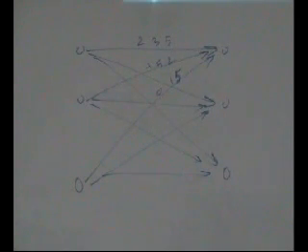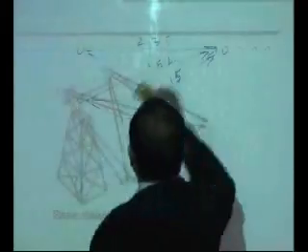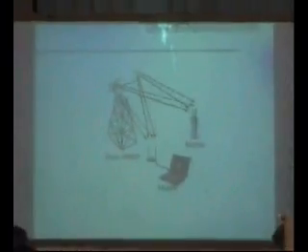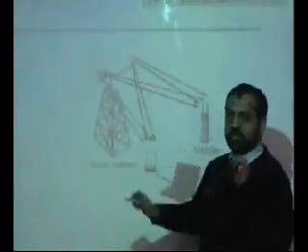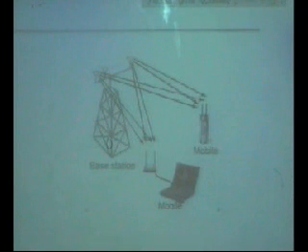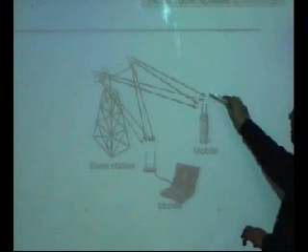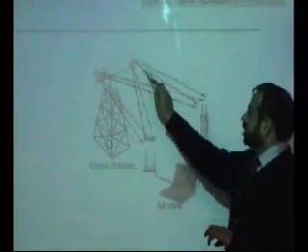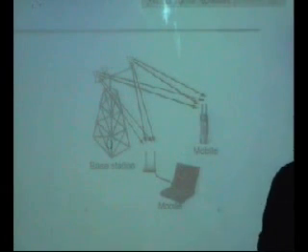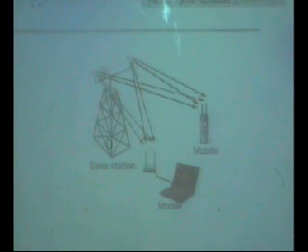So this is where the technology is moving, and these are called MIMO, multi-input multi-output systems. They are of special interest to us. Why? Because each antenna transmits a different stream of data. You are not transmitting the same data using all the transmitters. So what you receive at the receiver is not clean data from one transmitter; it is data transmitted from different transmitters, passing through your channel and hitting the receiver.